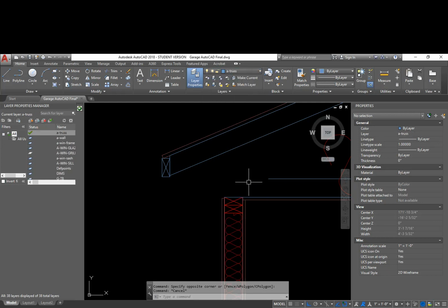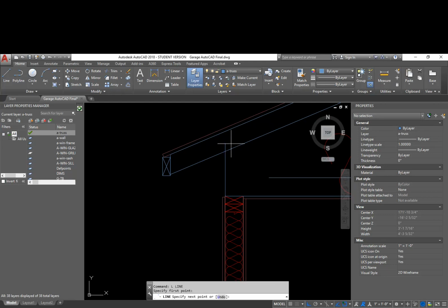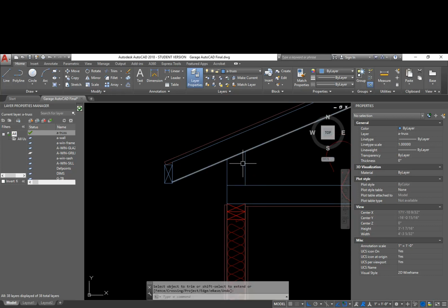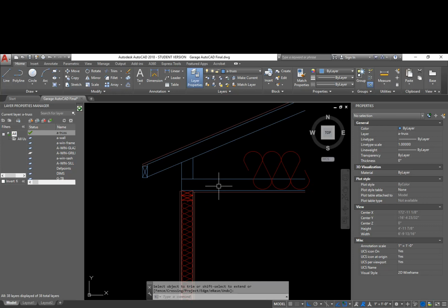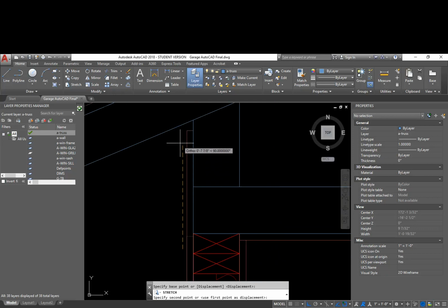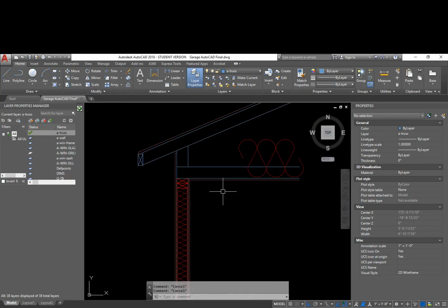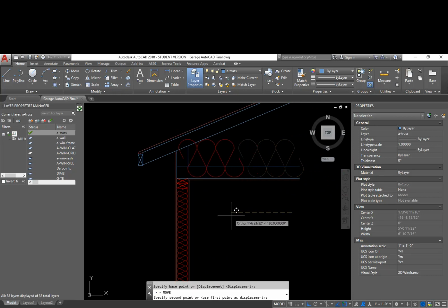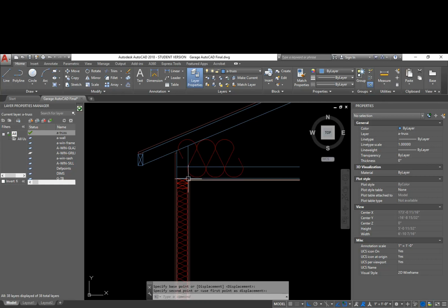And I find that, set that current. I basically have to draw something like this. And that's how the truss would look. And then I would just have to extend this OSB up past there. And now, whenever I put my insulation in here, I can run it the whole way out, having continuous insulation the whole way through the wall, the whole way out where I need it.